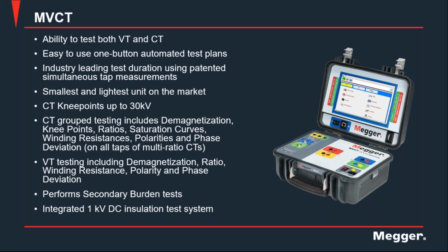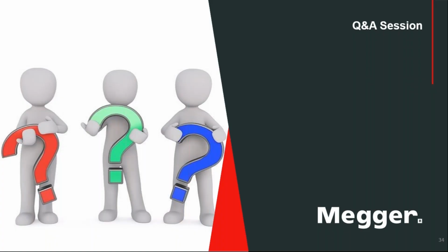It's a lighter instrument because now you don't have a transformer that goes up to 2 kilovolts, and it provides the same features as the MRCT, with the only exception that you cannot test CVTs with this one. You have to use higher voltage for CVTs, and so this instrument won't apply, but you can still test the insulation resistance. You can also test burden and do all the other tests, and it will perform the same assessment on all of the instrument transformers that it can test.